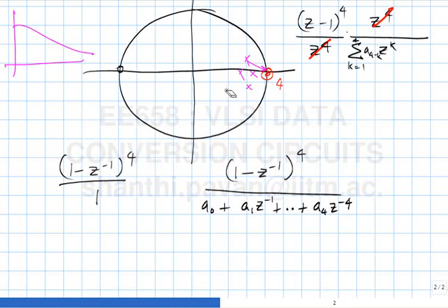In many practical situations it turns out that indeed becomes the case because of non-idealities in the realization. But at this point, purely from a theory point of view, there is nothing preventing you from doing it. However, this is the canonical thing, right? So this is the transfer function which will give you the lowest order transfer function which will give you 4 zeros at z equal to 1 and a low pass type. And all the trick is in the denominator. By making a poor choice of a0, a1, etc. through a4, you can screw up big time, right?